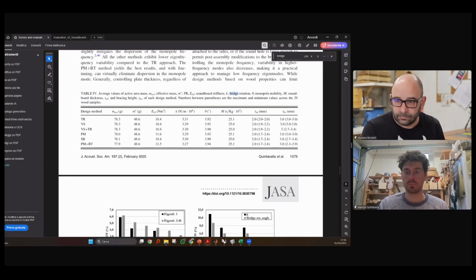1.7 then would be a particularly stiff piece of wood, yeah? Sorry, it's the thickness of the soundboard. I'm saying, the wood that you started with to end up at 1.7 would necessarily be a really stiff piece of wood, or not necessarily? I'm just saying that the stiffness becomes a negative in that situation because your board becomes impractically thin.